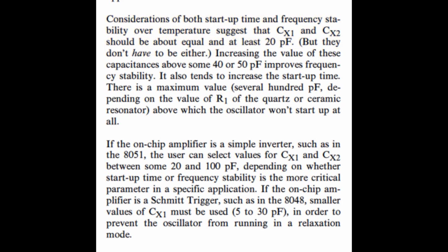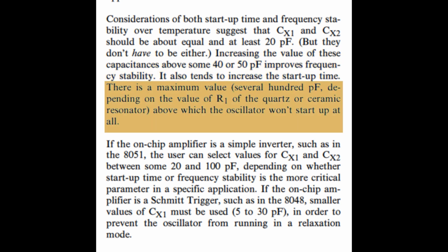What? Increasing the value of these capacitance above some 40 to 50 picofarad improves frequency stability? Yeah. It also tends to increase the startup time. No, it doesn't tend to increase the startup time. It does increase the startup time. But here's the howler, as we like to say. There's a maximum value, several hundred picofarads, depending on the value of R1, which is the feedback resistor, or it won't start up at all.